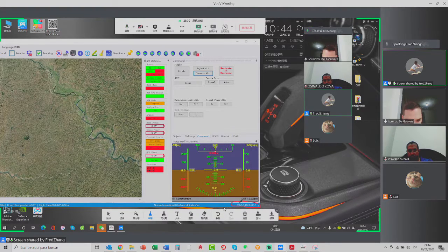How to make sure: the TX number will be increasing, and if the message packet comes back, the RX number will be increasing. So you must check that the TX number and RX number are also increasing the same, which means the whole system is working normally. You got it? Yes. All right.